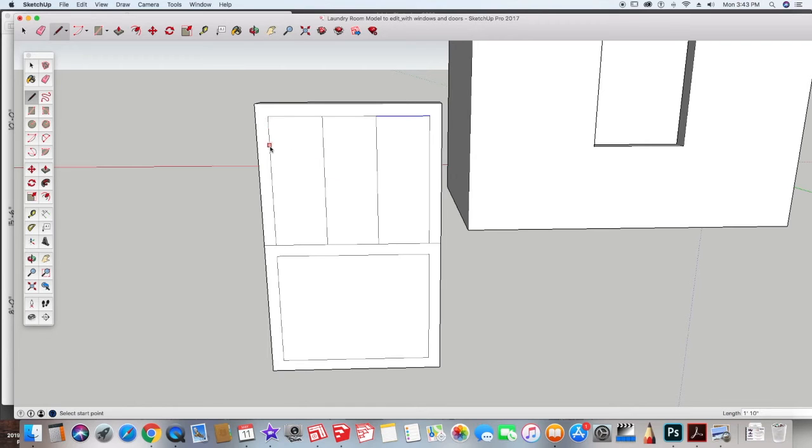We're going to take our pencil tool again and mouse along on the far edge to get that cyan point. One of the things that SketchUp doesn't like is if I were to click here and drag it across and click on the other side. It needs you to go to each point that you want to go to and click. When you go over it again, you're going to come to an end point and you're going to click again and go across, and then click again and go across. It does not like it if you cross lines. It can kind of mess up some of the geometry. To keep a best practice, we want to keep it this way. If I mouse over these, you can see that we have the 6 segments all separated out.